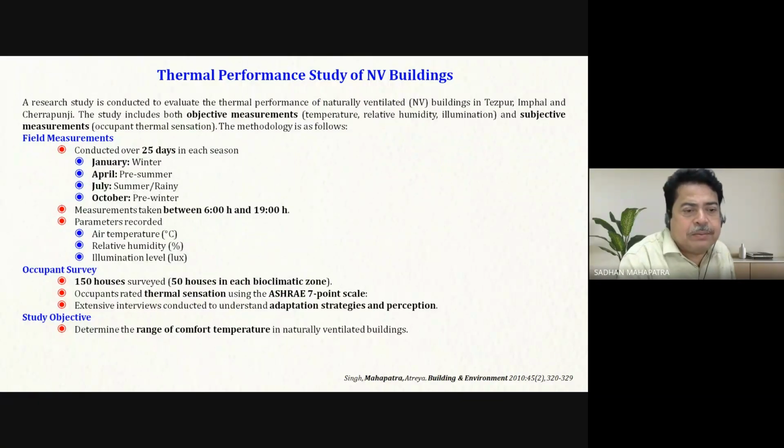So this is a study of what we have done in the naturally ventilated buildings in Tezpur, Imphal, and Cherrapunji. And this study also includes objective measurements like temperature, relative humidity, and illumination, and subjective measurement, which is the occupant thermal sensation. In the last class, we talked about the ASHRAE thermal sensation scale.